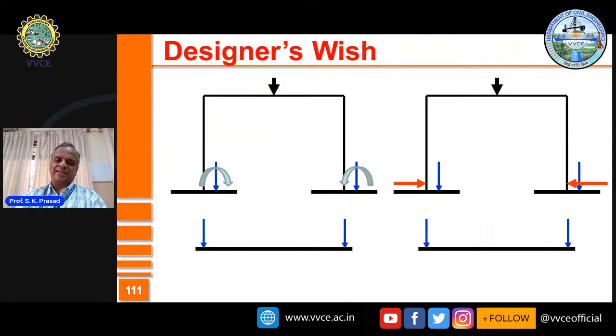So this is another interesting thing, because of the designer's wish I have mentioned. What do I mean by this? Let us say you have a symmetric portal frame. Under this column, you have to provide a footing. This column carries an axial load P and a moment M. This column also carries an axial load P and moment M. Because of symmetry, this is P, this is also P, this is M, this is also M. Most of the time, if this is a clockwise moment, this one is an anti-clockwise moment.